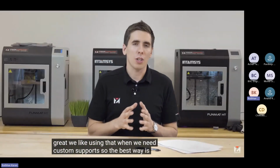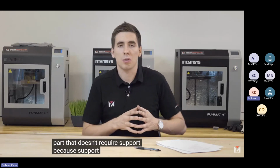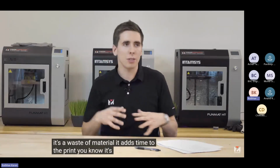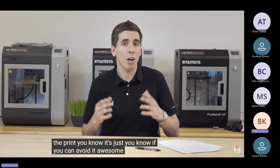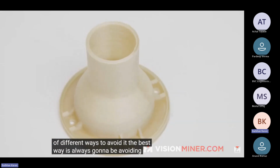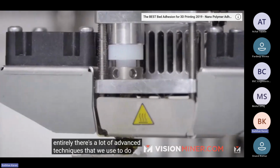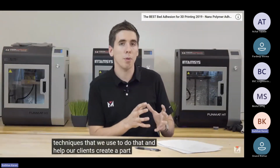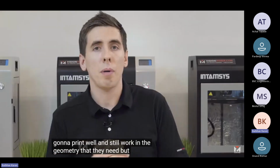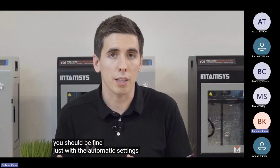So the best way is always to design your part or find a part that doesn't require supports, because supports can be hard to remove, it's a waste of material, and it adds time to the print. If you can avoid it, awesome. And there are a lot of different ways to avoid it. The best way is always going to be avoiding supports entirely. There are a lot of advanced techniques that we use to do that and to help our clients create a part that's going to print well and still work in the geometry that they need. But for beginners, if you're printing in PLA, you should be fine just with the automatic settings.